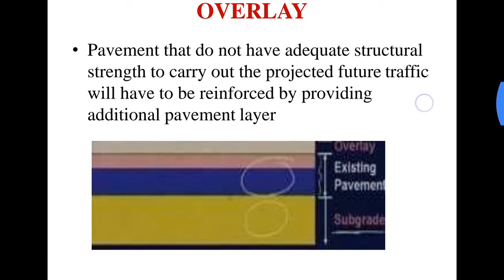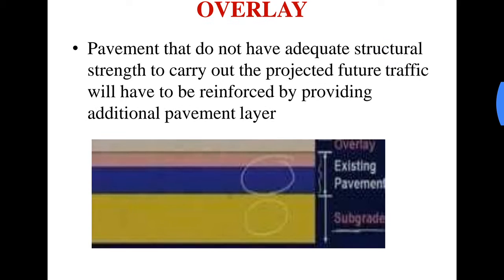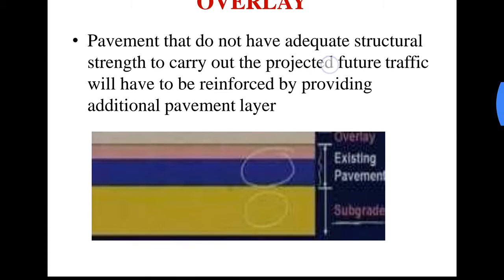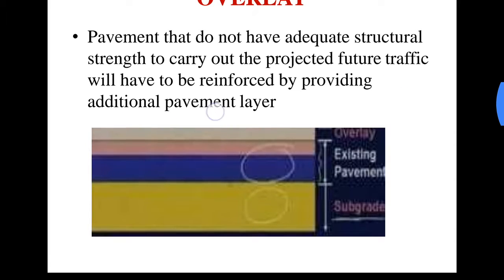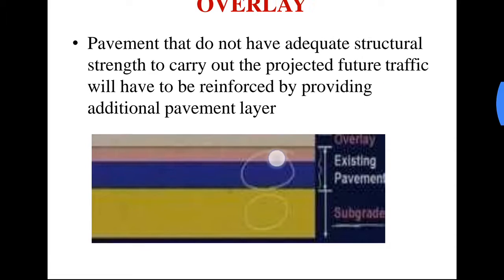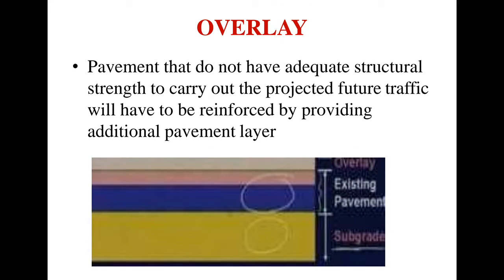Now, what is an overlay? Pavements that do not have adequate structural strength to carry the projected future traffic will have to be reinforced by providing an additional pavement layer. Okay, so on top of the existing pavement layer, if we provide an additional layer in order to increase the load carrying capacity of the pavement, that layer is known as the overlay.